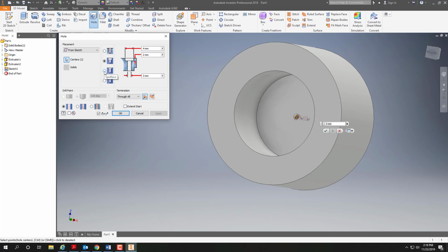Now, the next one down is called a spot face. Sometimes the spot faces are drilled, they are ground down just enough to have a level surface where the bolt can sit. And sometimes you'll see a spot face in a casting that actually protrudes from the surface, and it's there just so that they can machine that down to give a level surface.